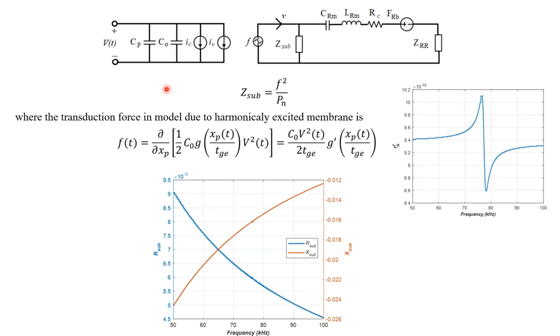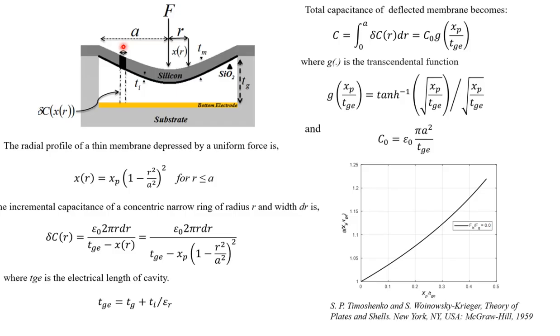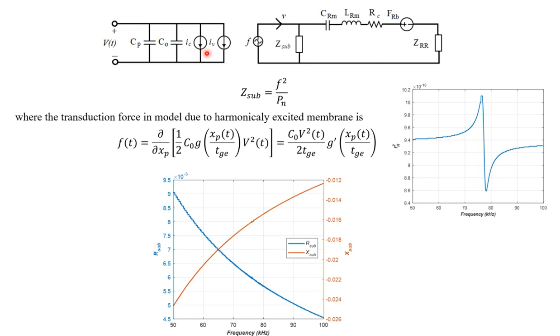So this goes into the model with the parasitic capacitance, which means that you will have some capacitance of wires or channels. Then when you apply a harmonic time-varying signal at the electrical side, there will be a change in the capacitance because of a vibrating plate, and due to the change in capacitance, you will have an alternating current, an AC capacitive current IC on the electrical side, as well as the particle velocity changing. So this is modeling the particle velocity of the membrane.